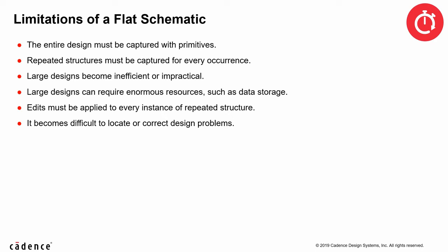A flat schematic becomes inefficient as more and more components are added to the schematic structure, since the entire design must be captured with primitives. If there are repeated structures, they must be captured for every occurrence. Therefore, large designs become inefficient or impractical as they require enormous resources such as data storage, and edits must be applied to every instance of the repeated structure. It even becomes difficult to locate or correct design problems in such a large schematic.